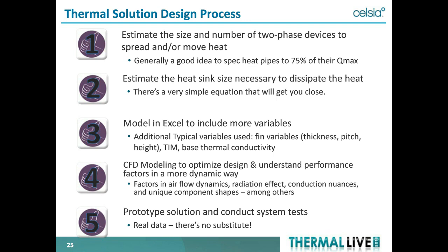Then what we do is we move that into an Excel model so that we can do some what-ifs, if I make the fins longer or shorter, that sort of thing. Once we think we're getting close, we generally move that design into a CFD model, and then obviously build something and get some test data.